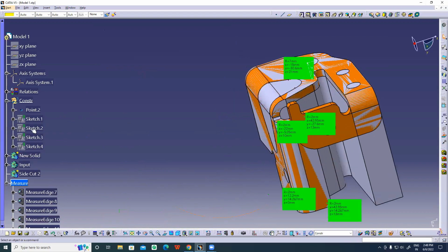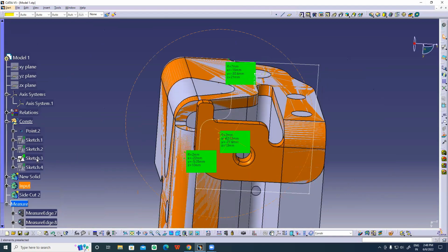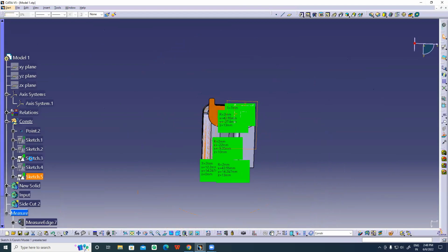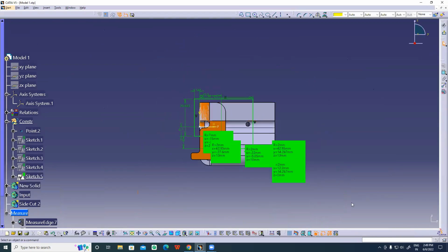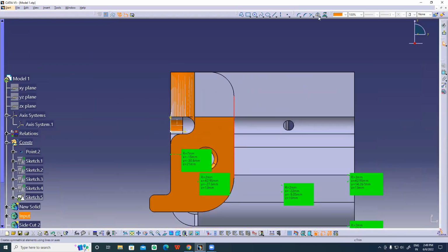Okay, fine. So now I'll be defining this, and I wanted to create a body with respect to this view, right? That means I can check the sketches. Are there any sketches already available? Yeah, sketch 3 is available in this plane, exactly in this view. I'll be copying sketch 3 and pasting it, and hiding sketch 3. Now it's created a sketch file. I'll go inside the sketch file, deleting whatever is available in it, and this is going to be my edge, projecting it and right clicking it, isolating this.